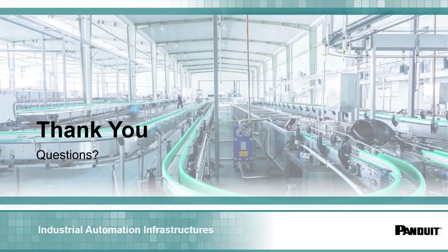Now that we're moving to Ethernet IP, we have a great deal of bandwidth capabilities, and so we no longer need to have the PLC as the center of the universe, but we can now move the industrial switch in there. And so one of the big advantages is, if you needed to have information sent from a limit switch or device up to the information system, to the MES level or SCADA system, you had to programmatically allow the pass of the data through the PLC.